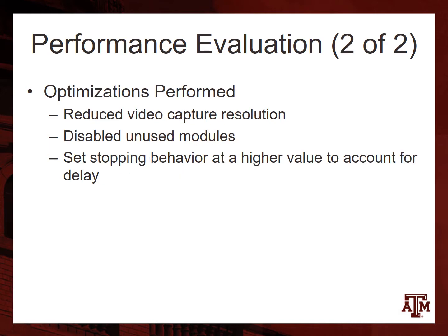To help achieve the performance obtained, we reduced the video capture resolution to save on processing power. We also disabled unused modules like GPS, compass, and accelerometer, using disabled structures to save on processing power. Finally, we set the stopping value higher to account for delay in frames.